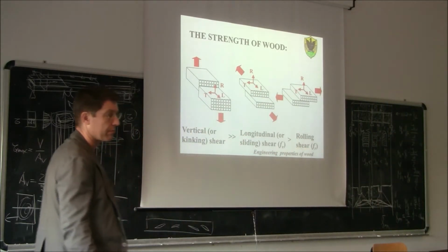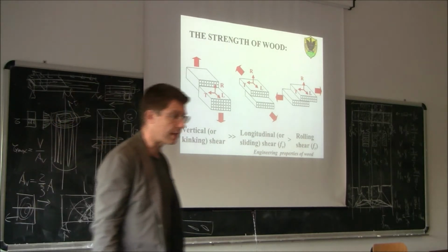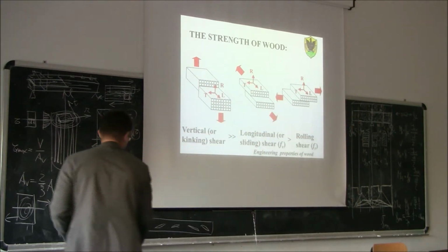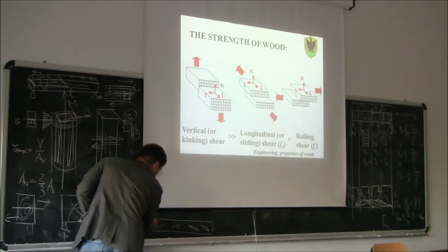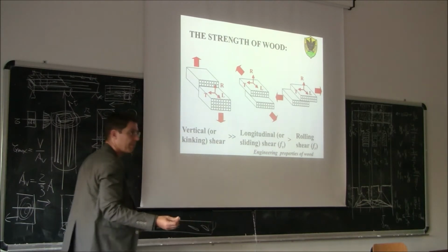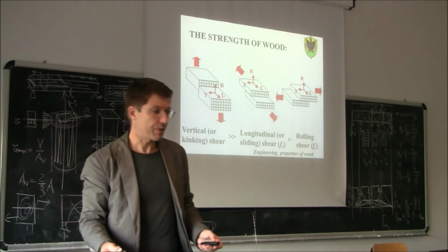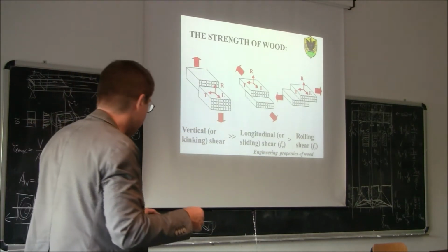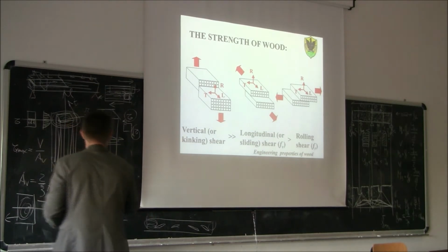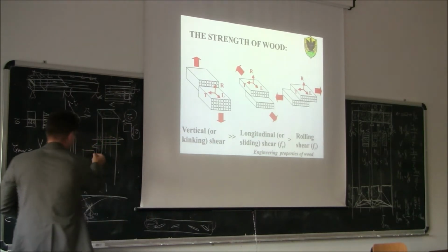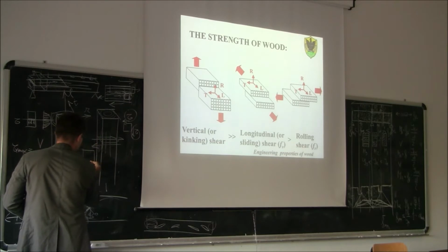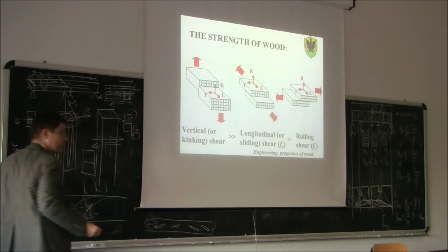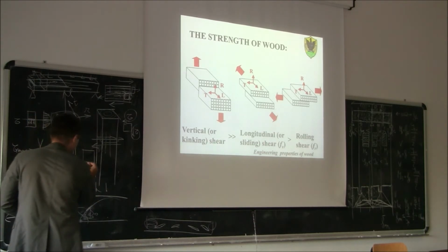Remember that if you need to check for a real shear failure collapse, you need to check it in the area where the shear is maximum, so basically over the support, if you have a simply supported beam. If you have a shear failure, you may have a horizontal or slightly inclined crack, and since this is going to reduce your strength, suppose that this is your beam, you have a shear crack like this.